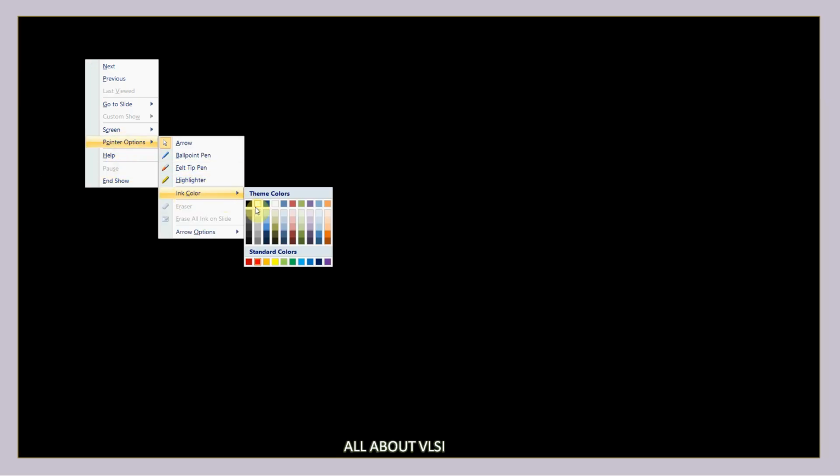So the very first system task, which we have already seen in our previous sessions also, is $display. This $display is used to print the contents into the console. Okay, so what is the format of this? If you see any keyword with a dollar symbol, then it is a system task.